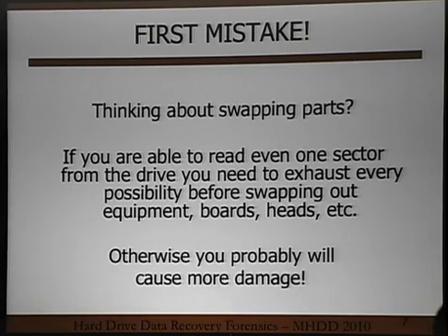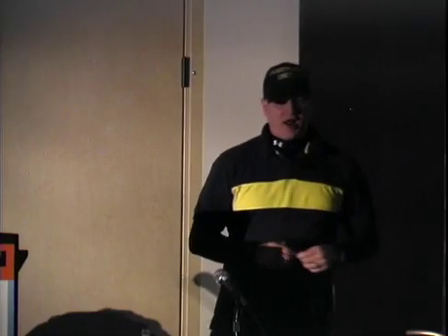Even with boards, you have to be very careful with going and buying an identical drive and then swapping the board. I know I've said that in some previous events, but some newer things have come out lately that can cause damage with the boards. And in certain drives like Western Digital's, you may need to unsolder a chip and move it. It may not do damage if you swap the board, but it's not going to work either. So you need to know that. I want to make sure you know, if you're thinking about swapping parts, when do we actually discuss that? Where are we actually going to talk about practicing with the drive?